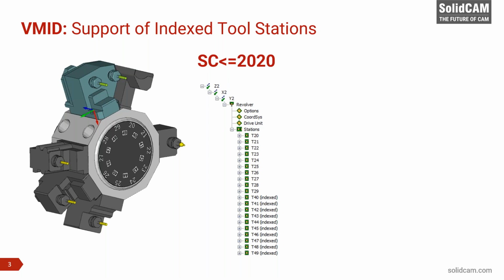As you know, you basically create additional stations, and this example has 10 stations. In this webinar, I will use this turret at the main point, as on the market, on most machines, you can find rotary turrets with 12 stations. This is very common, but today I'm going to use one with 10.